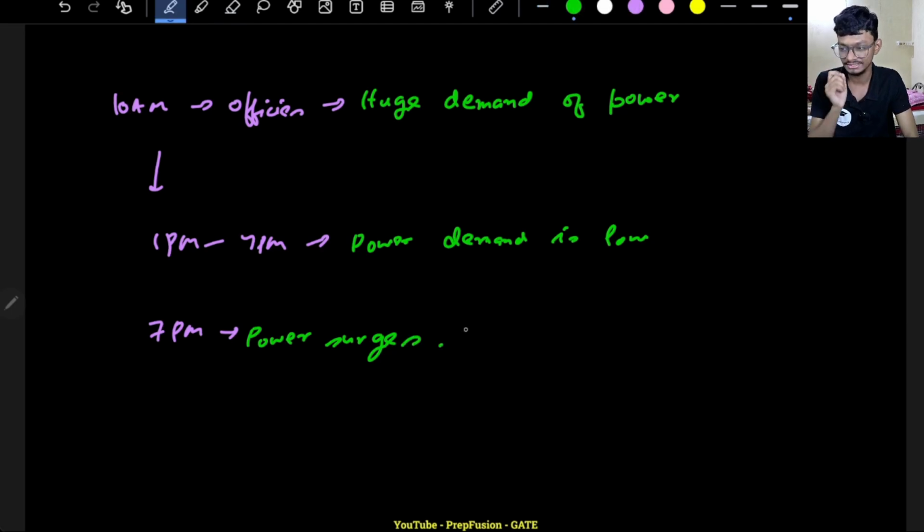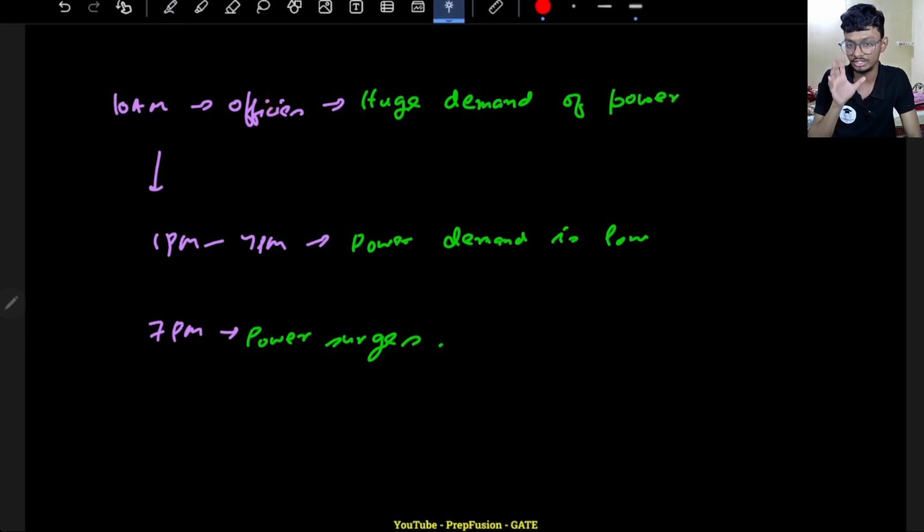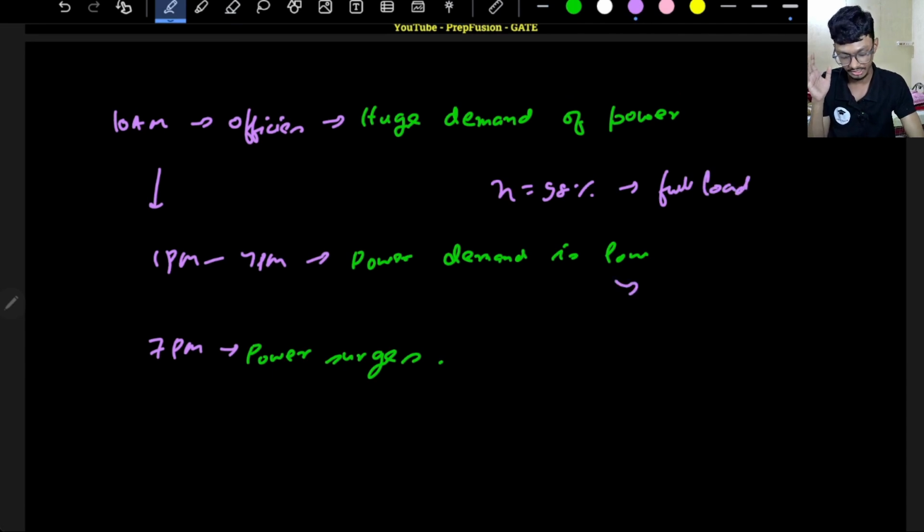So that is the problem here, right? If I just find out the efficiency for this particular load, that is not enough. I should know how my transformer is behaving holistically throughout the day. It's not enough if the efficiency of the transformer is 97-98% only at rated load or full load, but at half the rated load it is like some 70%.